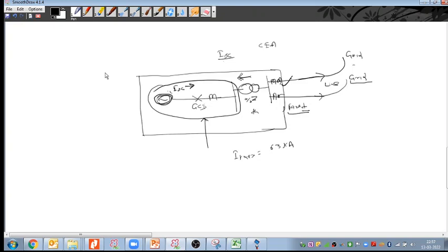You are telling that like generation one, but in the wind farm every individual generator is actually 1.5 or 2 megawatt. Generally they will have 10 megawatt or 25 megawatt as one feeder. In that scenario we will consider the 25 megawatt feeder as the generator total amount, right? Right, Ganesh. Okay, thank you.